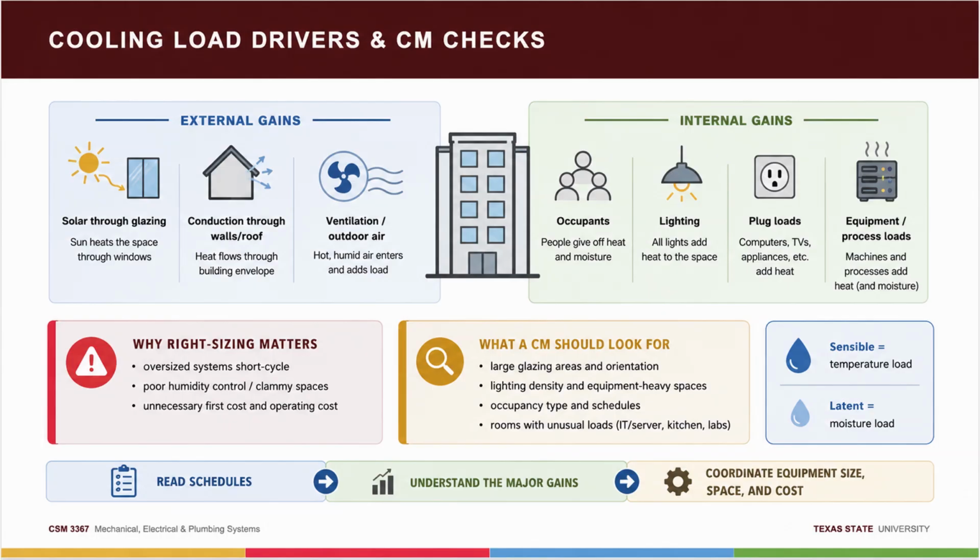The bookkeeping term for all this, the study of air and moisture mixtures, is psychrometrics. Engineers live on the psychrometric chart. You don't need to master the chart in this course. You need to know it exists. Know that grains of moisture is how engineers count water in air, 7,000 grains to a pound.